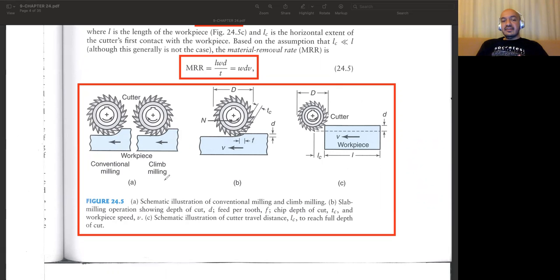If you have a gear pair, since we cannot have a continuous contact with the teeth of gears, at some point we cannot transfer the motion, and this is highly important especially if you are changing the direction of motion. Once you change the direction, we will be losing the contact between the teeth, and we will not be able to transfer the motion to different mechanical components.